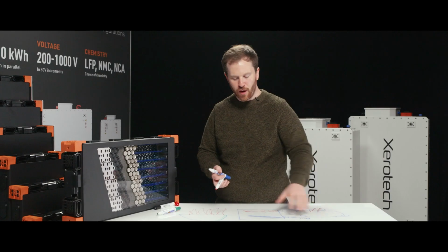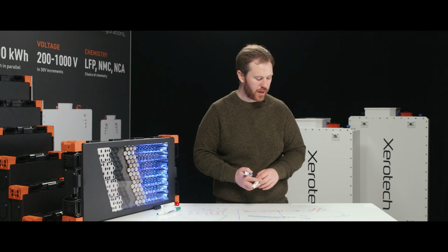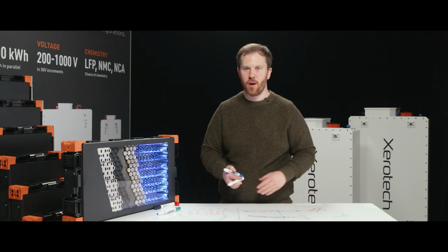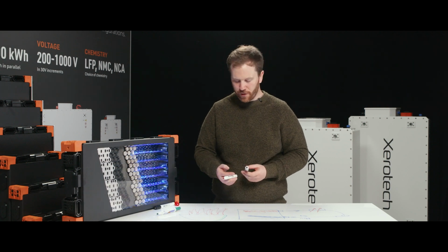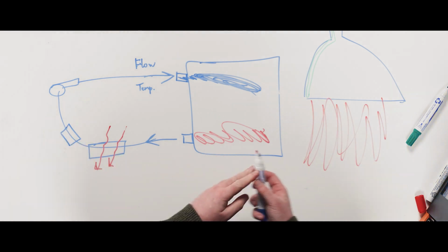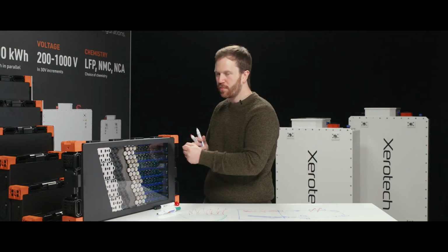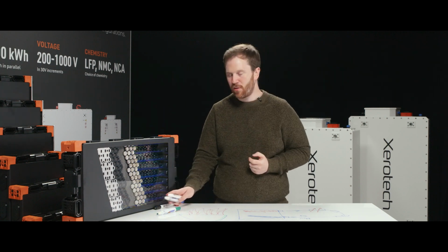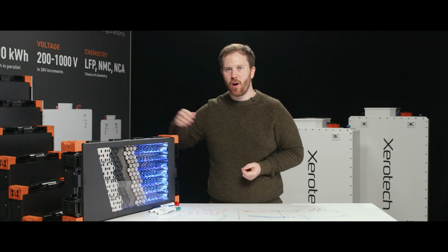So overall, battery thermal management systems have a number of different subsystems inside of them. Another heat exchanger that either raises or decreases the temperature of the system. In some cases, it might just be a heater. It's like having that kettle we spoke about earlier inside in the battery, where you just preheat it. And that's where some battery systems may have internal heating, is they use electric heating mats or an electric coolant heater.